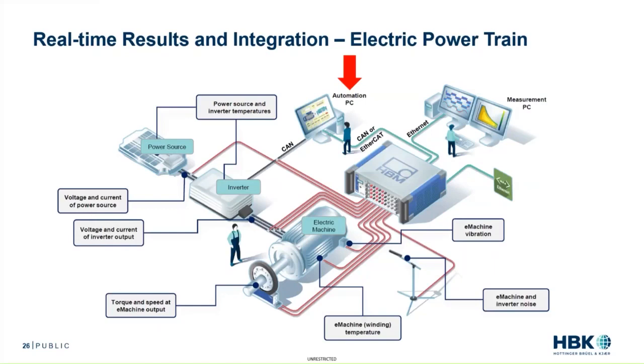So you want to be sure that the power analyzer that you're using can provide full data transfer to automation systems with refresh rates of, well, at least 500, sometimes 1,000, maybe even up to 2,000 results per second. This means that your dyno, aka the automation control system, will get results when needed.